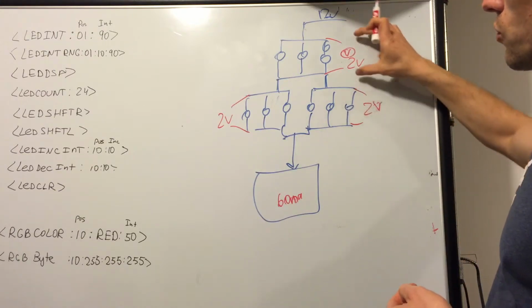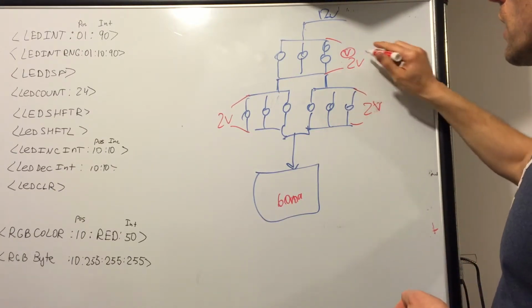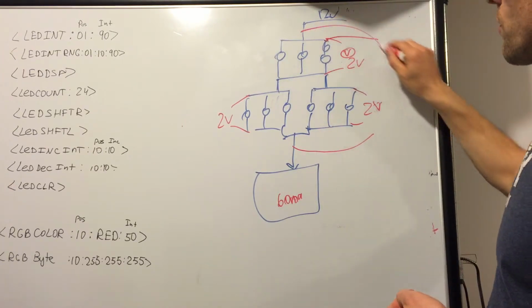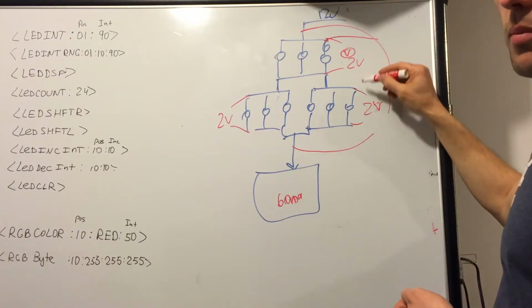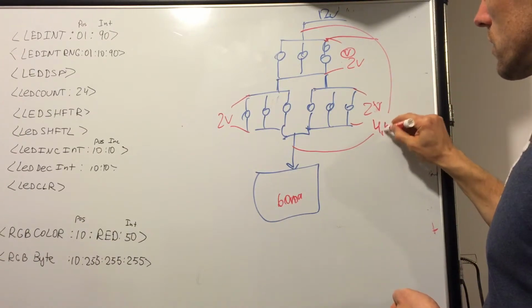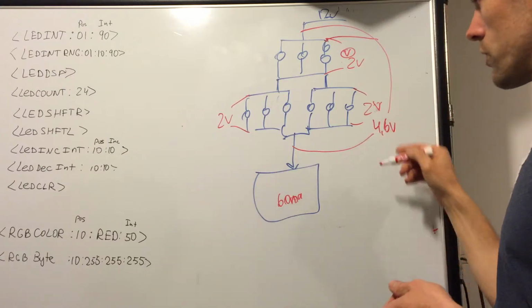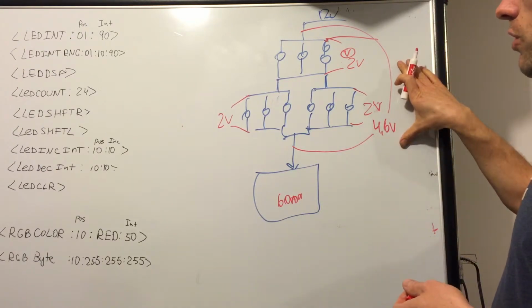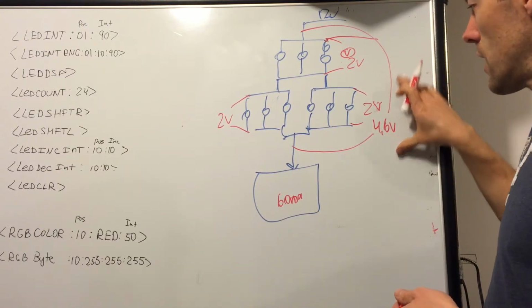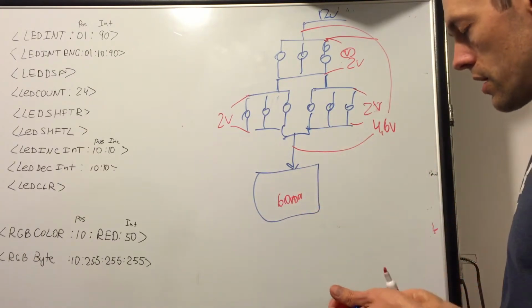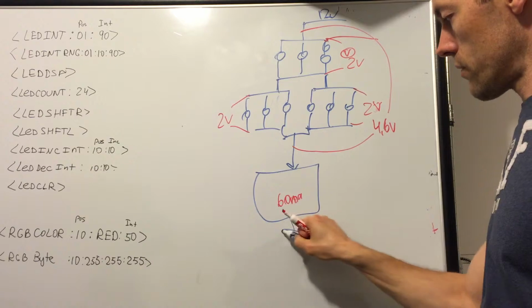But those 2 voltages are going to sum up. So the total voltage from here, basically from here, is 2.3 plus 2.3, it's 4.6. So we know it's the situation today. We have a 4.6 volt drop on the LEDs, and whatever is left is over here. So if you would measure, this goes to the ground somewhere.